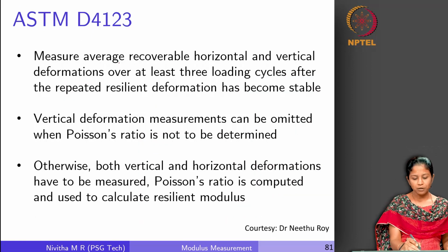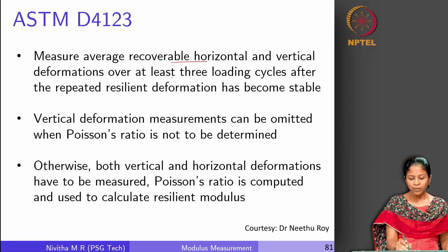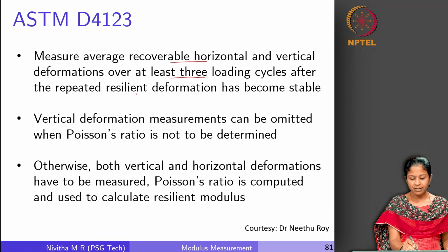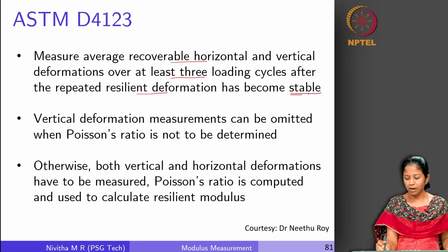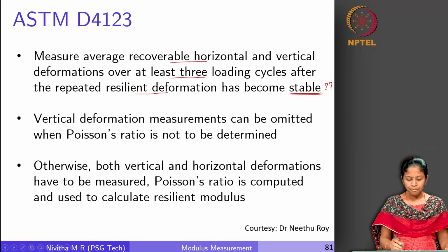Now, we are supposed to measure the average recoverable horizontal and vertical deformation over at least 3 loading cycles after the repeated resilient deformation has become stable. Now, when does it reach this stable state? It is a cause of concern, as I had mentioned to you earlier, right.